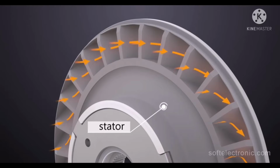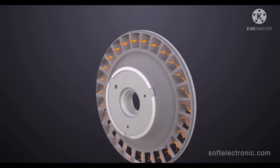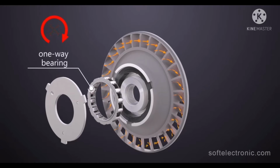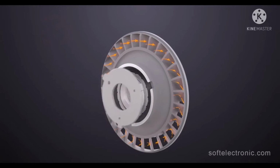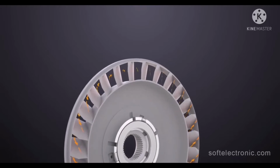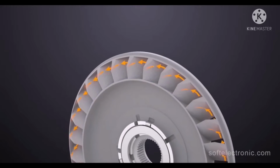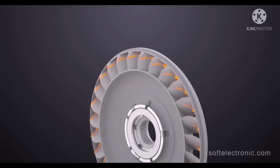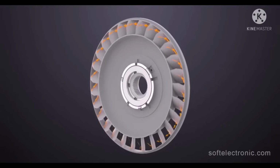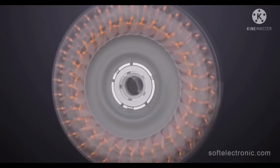At lower speeds, when the fluid passes through the stator, it causes pressure at the front of the blades and forces the stator to move backward to the pump and the turbine. To prevent this movement, the one-way bearing does not allow rotation in this direction. As the speed increases, the fluid velocity increases, and instead of causing pressure at the front of the stator blades, it begins to press the blades in the rear, forcing the stator to rotate in the direction of rotation of the torque converter. The bearing then releases the lockup and the stator starts to rotate in the direction of the pump and the turbine. The operation of the stator contributes significantly to the efficiency and increase of the torque converter.